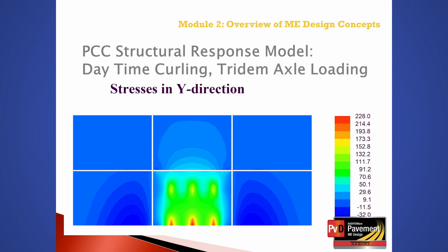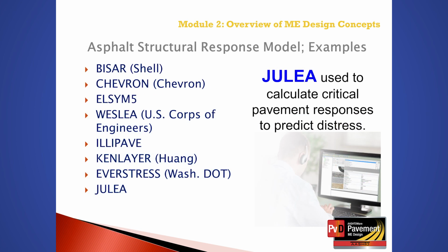The impact of curling is critically important in rigid pavement analysis and design simulations. Some of the structural response models for flexible pavements analysis are included on this screen. Julea is the elastic layered program that the pavement structure or software uses to compute critical pavement responses.